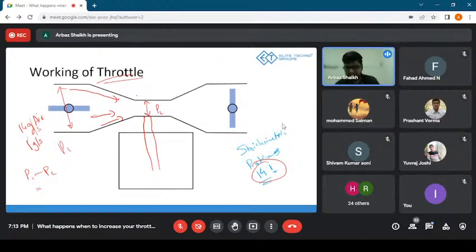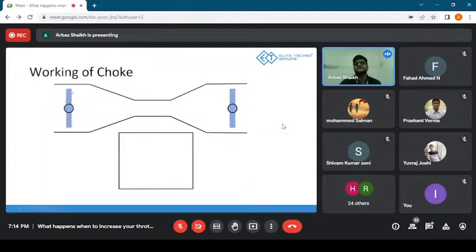Correct. Okay. So what happens is basically, when you're starting the vehicle, the throttle is not much given. The throttle is not increased. So whenever you start your vehicle, it's not recommended to increase the throttle. And when you're starting in cold conditions, you need the engine to work with a higher fuel. You don't want to work it at stoichiometric ratio, because if it does, it wouldn't start properly, right? And for that, what we do is we close up the air inlet of the Venturi, and a very small amount of air would enter from the side, something like this, right?